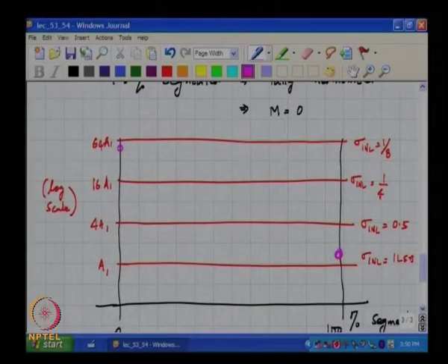In other words, this represents the area needed for the unit element to achieve a given sigma DNL, when the DAC is fully thermometer decoded. Now, can you comment on what happens when the same DAC is realized as a fully binary decoded version? What would the area required be?